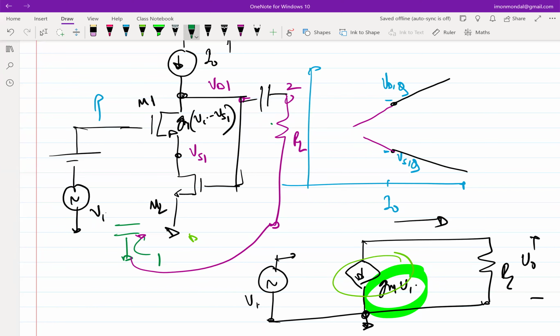That is through a capacitor, and a capacitor is one of those things that you can keep on adding, assuming it's not infinitely large, and you size it in such a way that you find out the time constant associated with the capacitor, and then see whether this time constant is large enough with respect to 1 over omega naught. If that is true, then it's shorted.